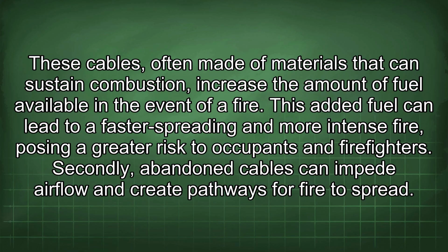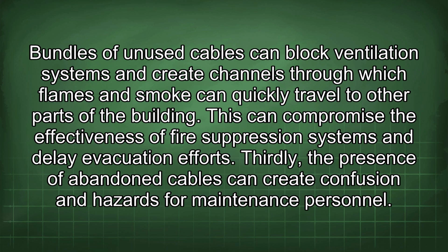occupants and firefighters. Secondly, abandoned cables can impede airflow and create pathways for fire to spread. Bundles of unused cables can block ventilation systems and create channels through which flames and smoke can quickly travel to other parts of the building. This can compromise the effectiveness of fire suppression systems and delay evacuation efforts.